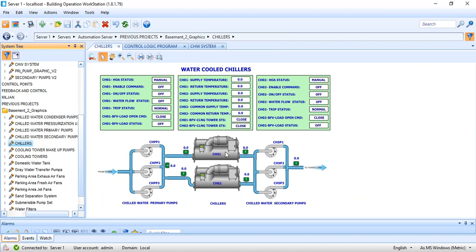So first, what is the difference between water cooled and air cooled chillers? It's very obvious. Water cooled chillers are using water to cool the chillers. Actually, what they are cooling is the refrigerant. So water cooled chillers use refrigerant, and likewise air cooled chillers also use refrigerant to chill the water. But in air cooled, they are using air through a condenser, an air condenser.